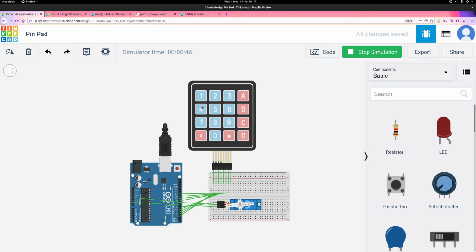And this is basically just a grid of a bunch of buttons. So it's a button here, button here, button here, button here. But you'll also notice coming out of this is only 1, 2, 3, 4, 5, 6, 7, 8 wires. However, the very clever among you, or everyone, will be able to count that there are in fact 16 buttons, because it's 4 by 4.